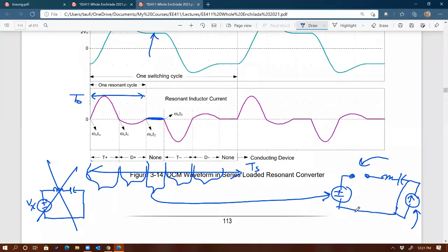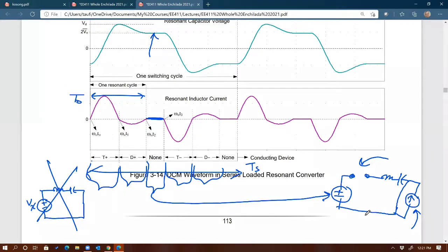Any question on this? I had a quick question. Yep. The output rectifier, is it allowing current conduction, so the resonant circuit itself is able to continue to resonate even when the input is turned off? Is that what you're saying?